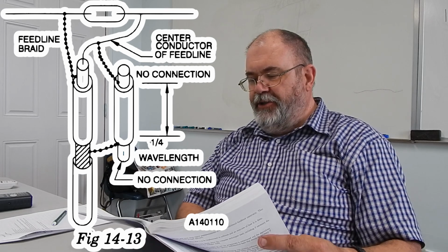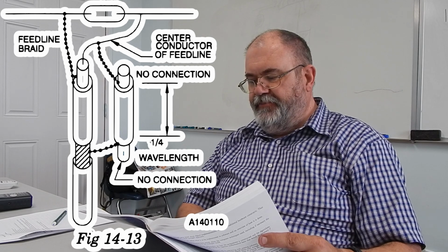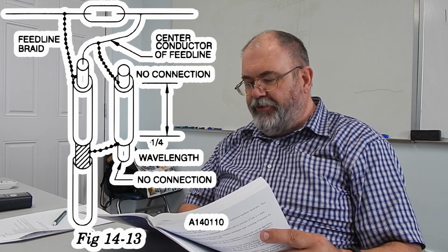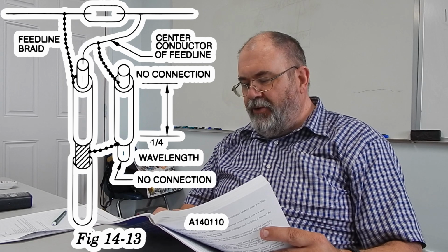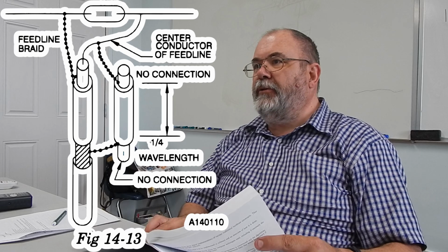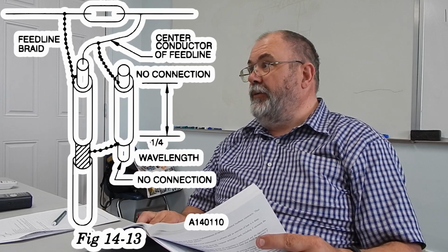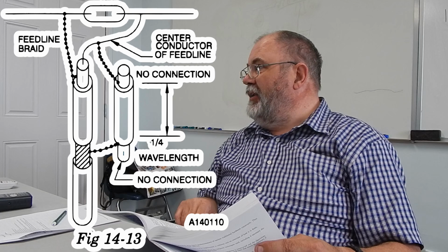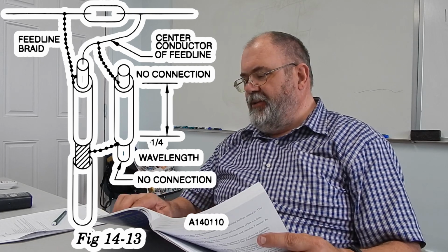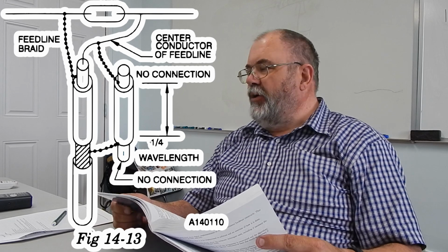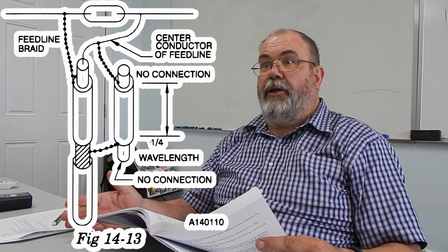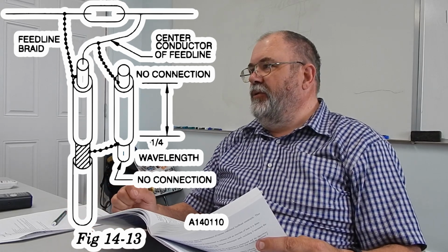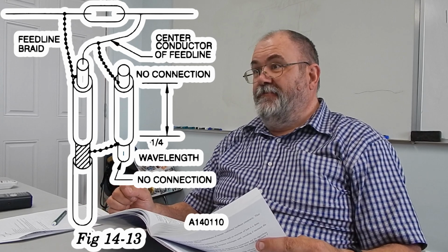And in the book, in that first paragraph under that section, I think it's the second sentence, it says equal and opposite currents flow on the surfaces of the coax cable feeder and the quarter wave coax stub section. So if they're equal but opposite, that means they cancel out. So going back down to the transmitter, you have your lovely balanced line and your RF's not going back that way, but the antenna is acting balanced. Works really good, but it only works really good at that one narrow band of frequencies that the quarter wave is cut for. So you would have to build that for every frequency you want to run.